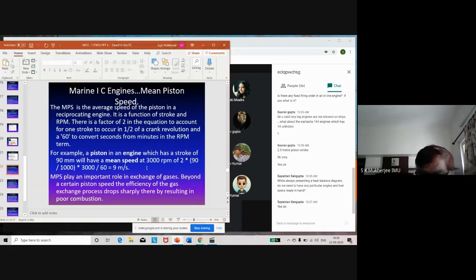Now, if the piston is moving too fast, by the time the air can come in fully to the required pressure, the piston has already reached its BDC and is on the compression stroke, so the valves have closed. In other words, the gate has closed. That is the limitation on how much air can come into the cylinder. This is called volumetric efficiency. The piston speed will determine the volumetric efficiency of an engine, that is, the mass of air that can come into the cylinder, given a permitted stroke length.